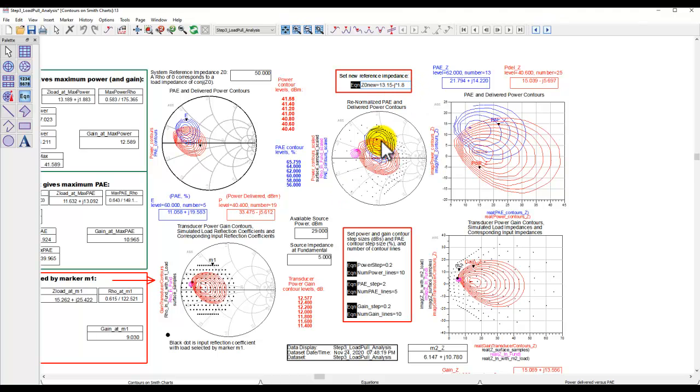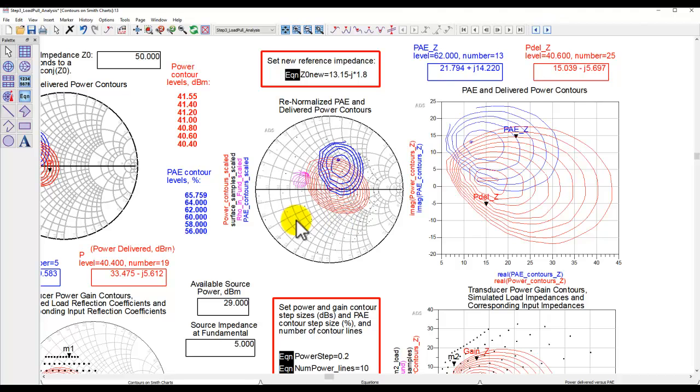So the Smith chart is a normalized plot, and you can unnormalize it to any impedance. So I'm going to unnormalize it to this impedance so that I have a zoomed in view of this region. Now in this particular case, it's kind of still okay, but in some LDMOS or certain GaN devices, you might be operating very close to the periphery of a Smith chart, and that doesn't make your job much simpler. But by bringing that operating impedance to the center of a Smith chart, now suddenly you can have a more comfortable view of looking at your data.